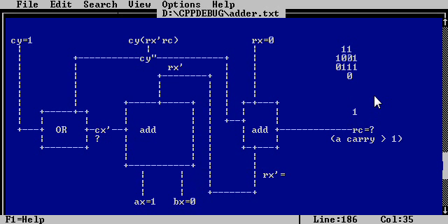And that leaves only one more case. And if the last case works, we're done. So that's everything 1. What happened? What should happen is that we should get an output of 1 and a carry. So let's see what happens. If you do 1 plus 1, the output here will be 0. But there will be a carry. So there will be a carry coming in here, and so this will actually be a 1.